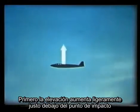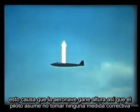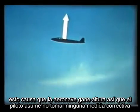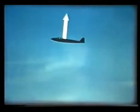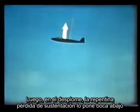First, lift increases slightly just below the shock stall. This causes the aircraft to gain height. That is, assuming the pilot takes no correcting action. Next, at the shock stall, the sudden loss of lift puts it nose down.